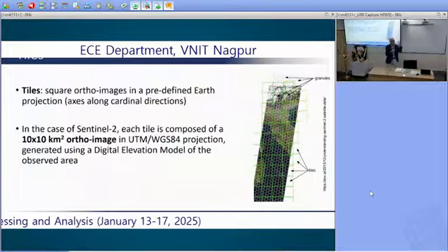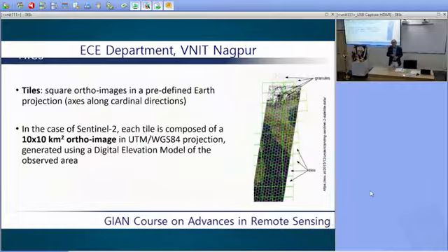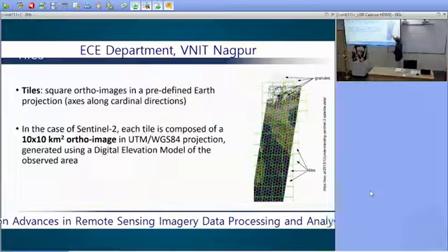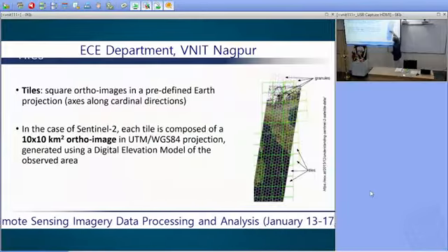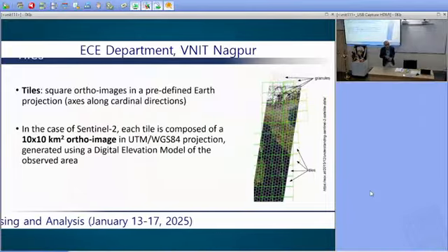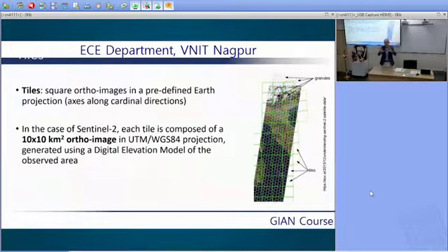When we download data from the portal, we don't download the original data. Those data are not accessible in most cases. In some they are, especially for other data, because they can be used for some types of processing. But in the case of Sentinel-2, you don't access the layer behind this. You access the tile, and the data in the tile has already been reprocessed, to move the pixels from one grid to another.